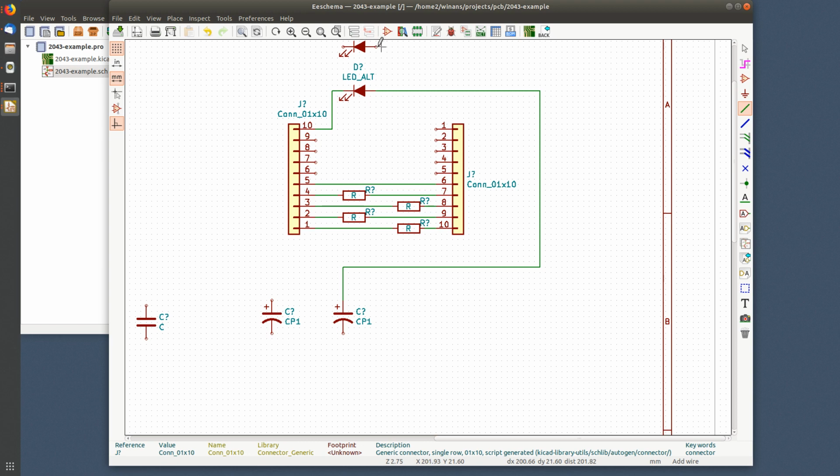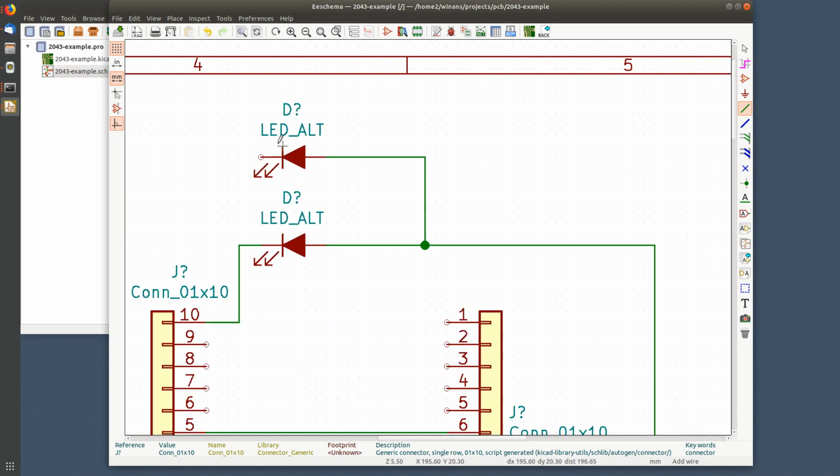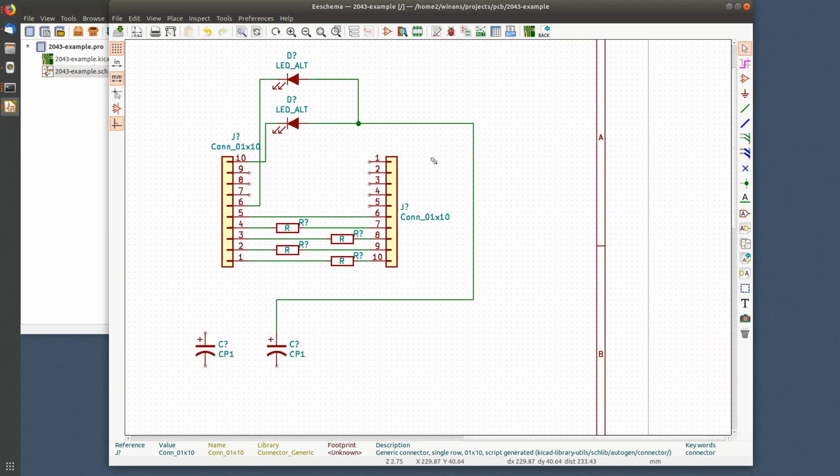All right, if you connect two wires together, I just left clicked on that terminal. I'll bring the wire down like this. If I click right there, I'm connecting the two wires together, and in the standard notation, if there's a dot right there, those wires are connected. If on the other hand I grab a wire from this LED and I come cruising down here like this, and I click left here, and then I click left to connect it to 6, these wires cross without a dot. Those wires are not connected. As always, hit escape and watch over here, and you're no longer placing wires. So there's how you place yourself some wires.